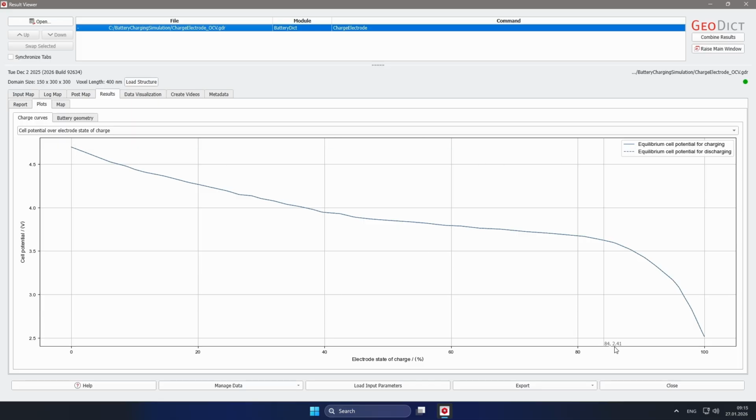In reality, the battery should also not be charged up to full 100% SOC or discharged until it's really empty. Usually staying within the voltage values for 5% SOC and 95% SOC is a good guideline. For a reasonable charging, we choose now a range between about 20% and 90% SOC, meaning voltage values between 3.5 and 4.2.